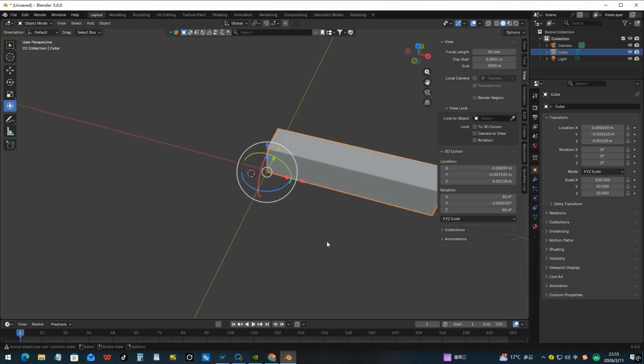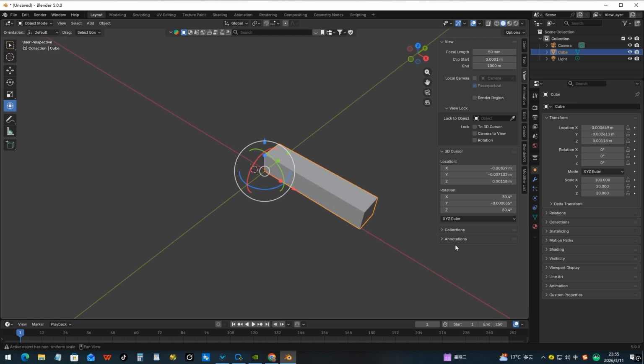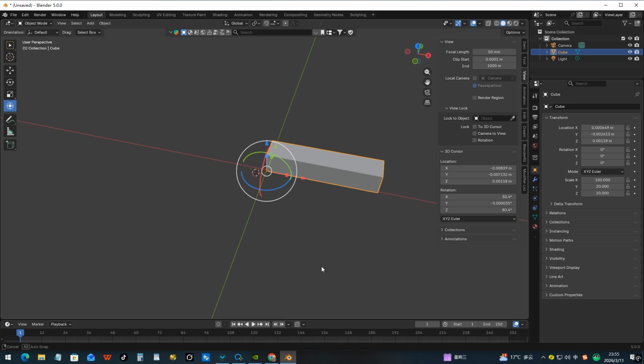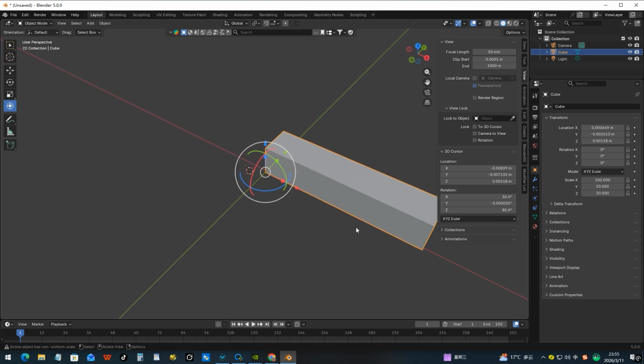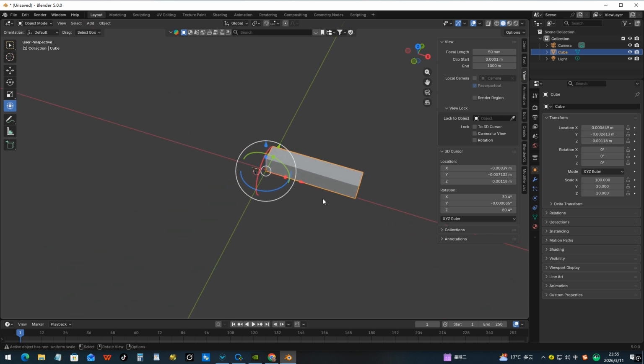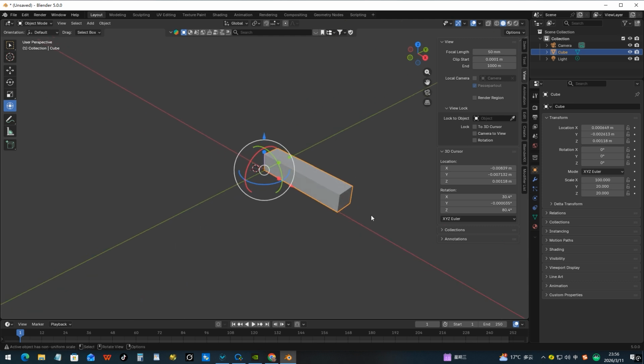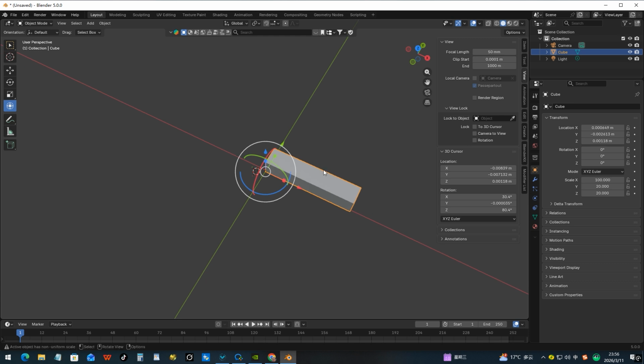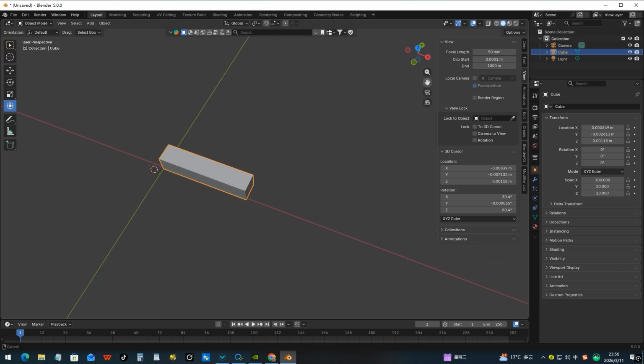Okay, so what do we do now? So this object is, as we can see here, 100 millimeters, 20 millimeters, 20 millimeters. So what we want to do, we are going to test different tolerances. We are going to put another object into this object. So what we do during the printing, we need to connect the objects in a right way, to stick them together, or to put them inside. And what we need to do, we need to know the tolerances.